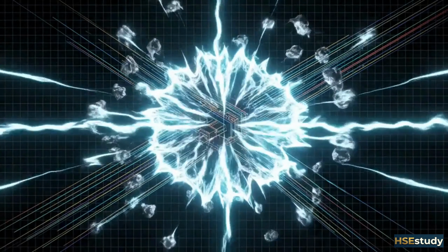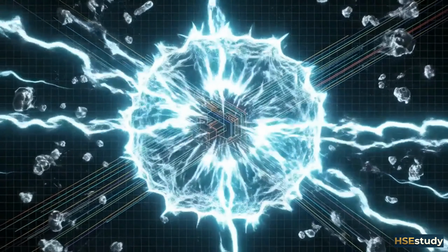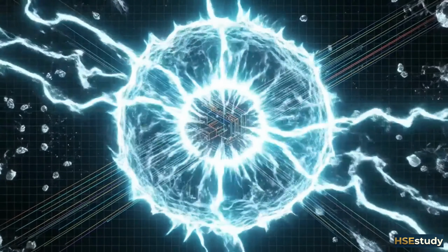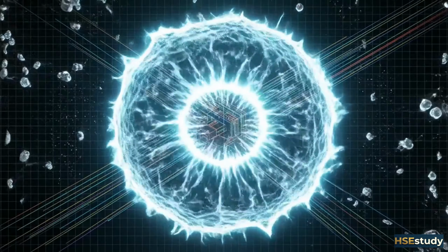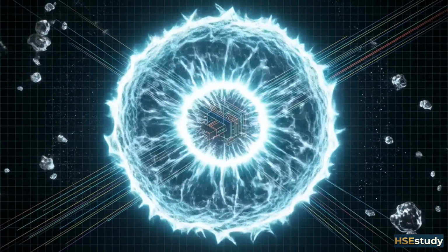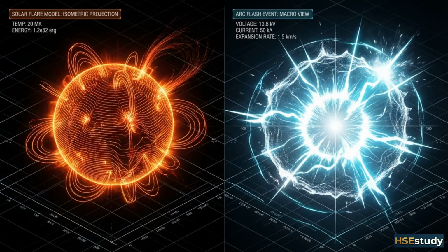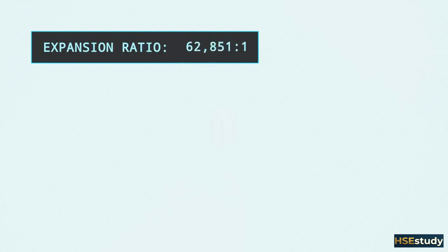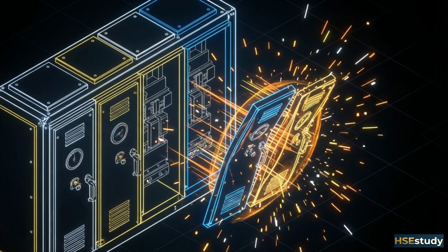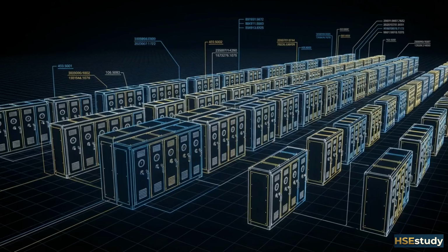When an electrical fault occurs inside industrial switchgear, solid metal vaporizes in milliseconds. The resulting plasma cloud reaches temperatures exceeding 35,000 degrees Fahrenheit, nearly 4 times the surface temperature of the sun. Simultaneously, copper conductors expand to 67,000 times their original volume, generating a massive concussive pressure wave known as an arc blast. This chaotic explosion contrasts with the predictability of normal electrical distribution.